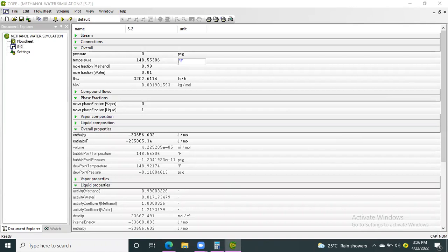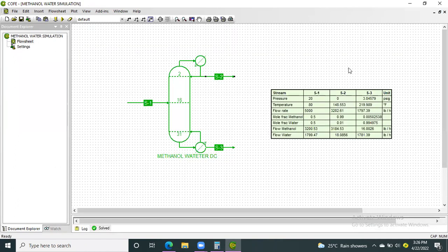I'll show you something. Let me see. Okay, so for us to use steam as a heat source, to heat up this liquid at its bubble point, so this is liquid at a bubble point, we need steam to be at a higher temperature. That's the requirement. The steam has to be at a higher temperature, so that it's a heat source, right?